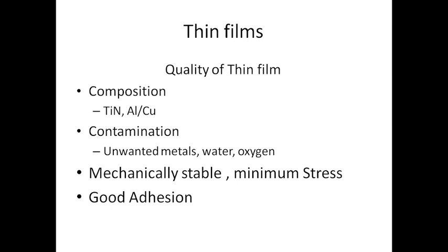And then, when we are depositing, contamination also matters. We have to see whether there are any unwanted metals that have been deposited during the process of deposition. Are there any water vapors hiding, being deposited over there, and is there any oxygen bubble or some gaseous bubbles trapped in the thin films. So these are the contamination. For a good quality thin film, there should not be any contamination.